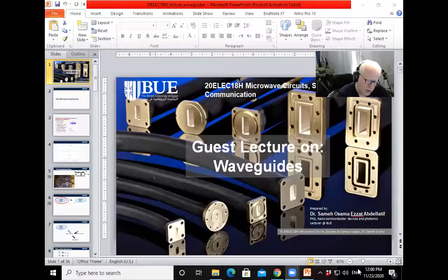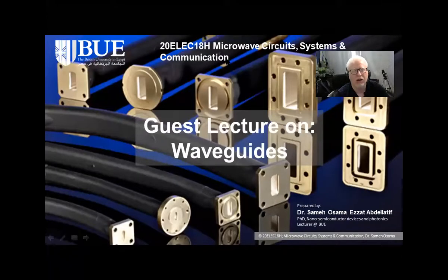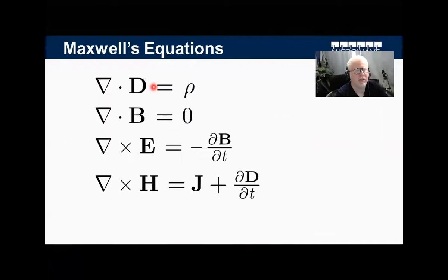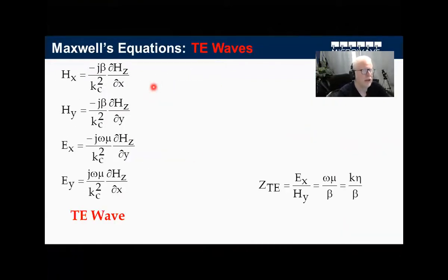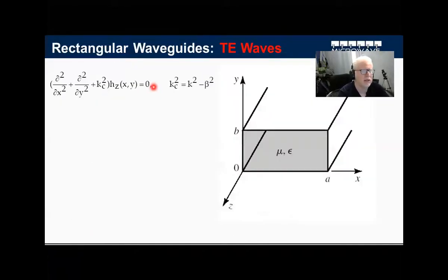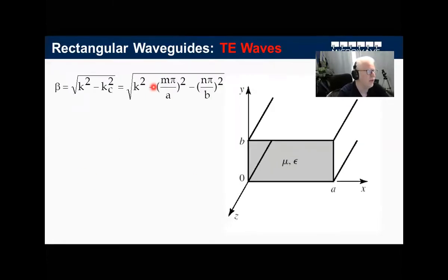Okay, so first we are going to flash back the main output we reached by the end of part number 3 in this lecture. If you remember, my dear students, we investigated deeply what's called the TE10 mode. Actually, we chose this TE10 mode basically because it is the fundamental mode in our rectangular waveguide.